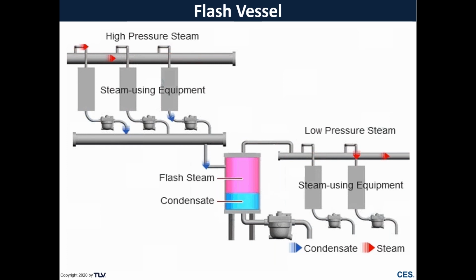So it's important to ensure that our high pressure steam using equipment maintains a pressure above that 50 psi to maintain positive differential and ensure the condensate can drain down to our flash tank. If we run into a scenario where we don't have that differential, that's when we have to start considering using something like a PowerTrap instead of using a steam trap in those instances.